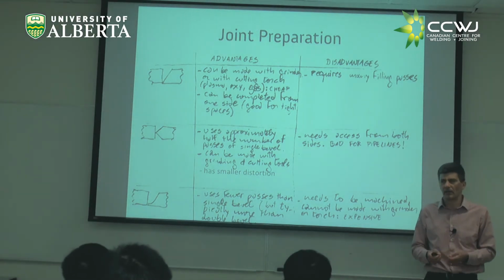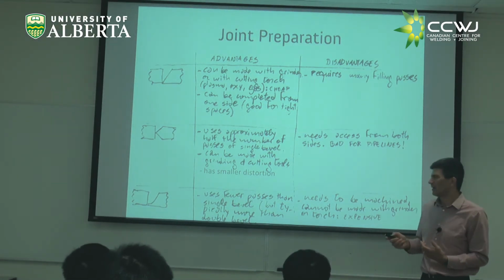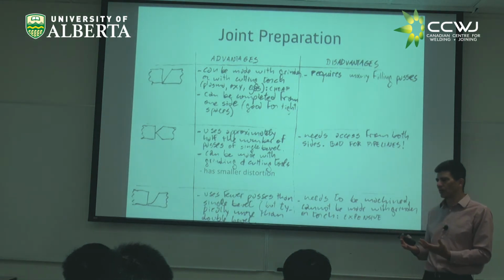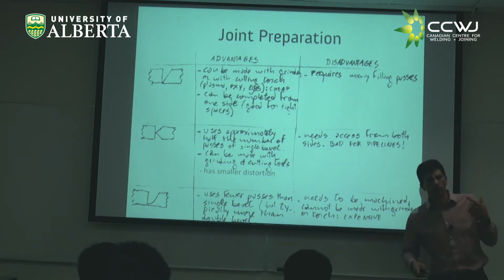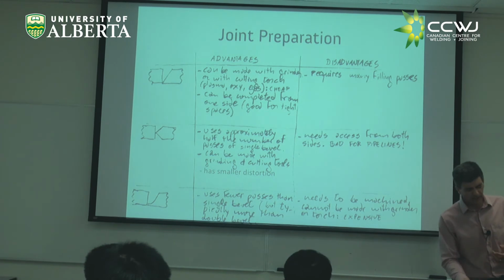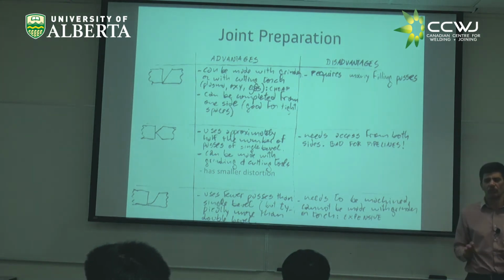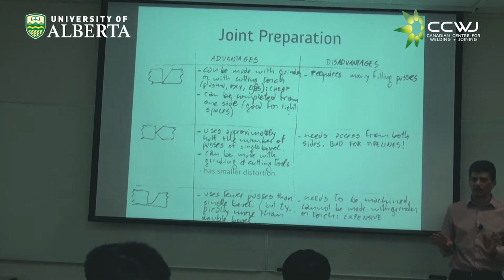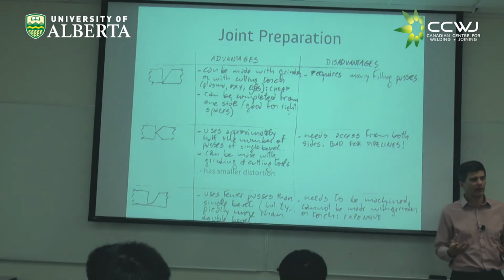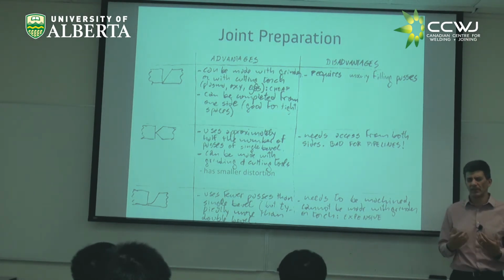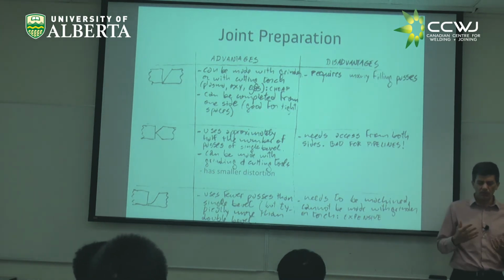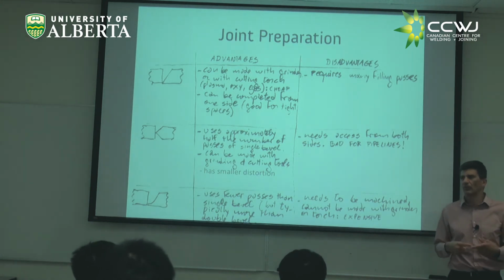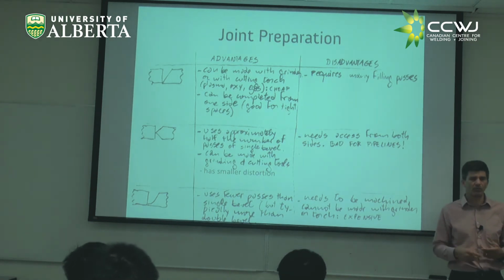You cannot just flame cut it and go with a grinder, right? So do you have this thing for machining the joints? If you have it, this is awesome. If you don't have the machine, you have to think, do I want to do this capital investment? In welding, everything you can do, you want to do, you can do it. You might not want to pay for it. That's the catch. So as we talk about welding, and we're going to have formulas and science and lots of amazing things, you're going to see that the real deal is not whether you can do it or not, but is, can I do it in an economic way? Do I want preheat, or do I want post-weld heat treatment?